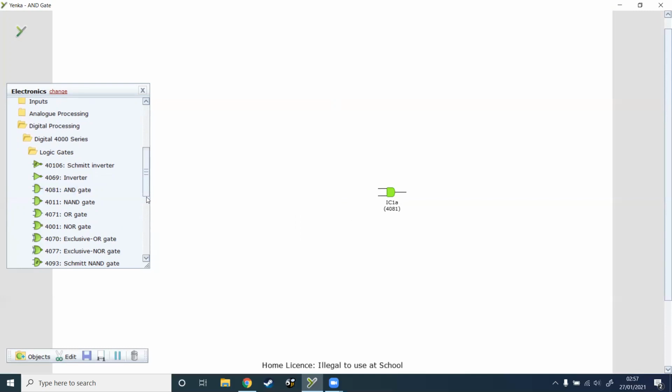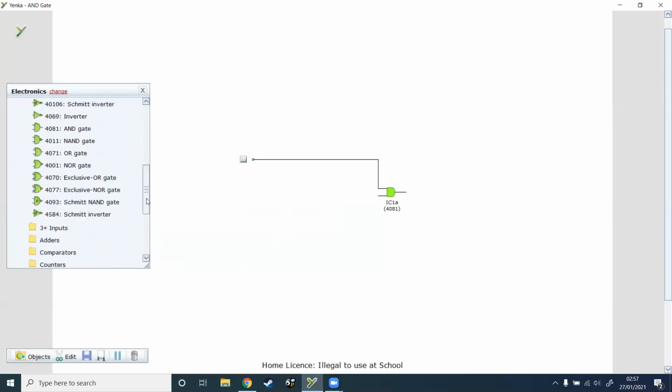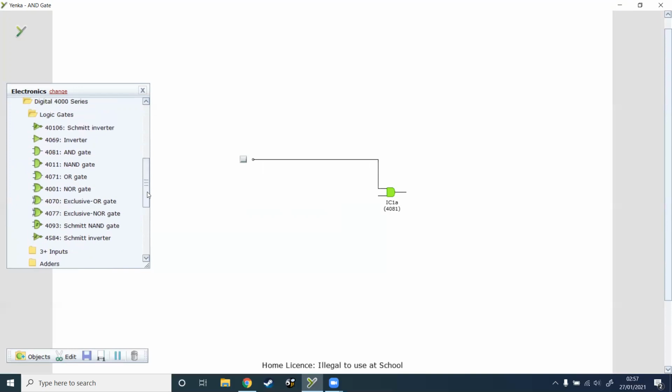One of the conditions is the input that the switch is on. So I'll take one of our latching switches and connect it here. That's our master switch, and we can label our diagram in a moment. The other condition that needs to be met is one of two things: either the light beam is broken or the pressure pad is pressed. So I'm going to have an OR gate here to divide those two up, and the OR gate will be the other input to the AND gate.